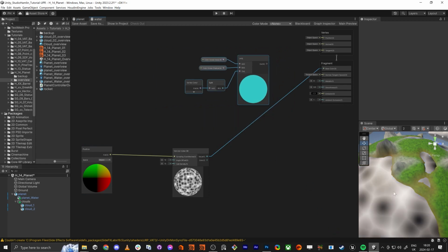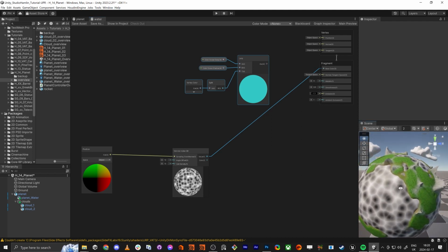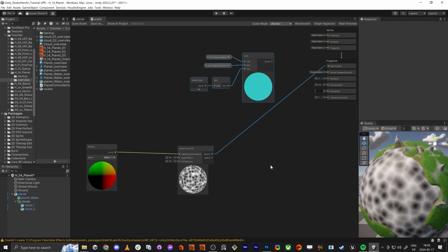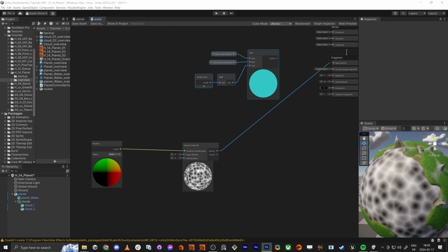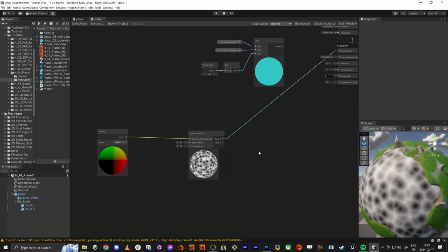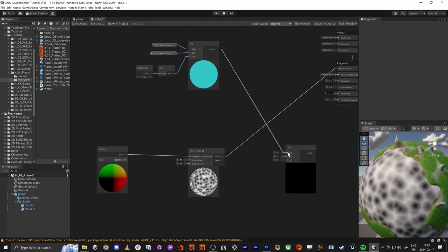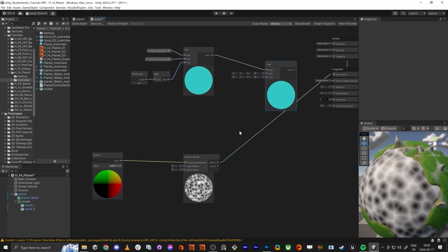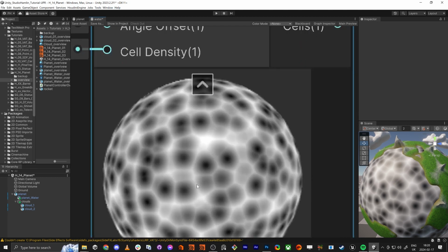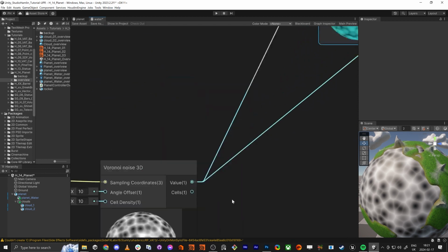And you see we're starting to get these wavy shapes, right? And we want to use this as a mask. So if we do a lerp, and this is the base color that we made in the previous tutorial, and if we do this one, then everywhere where it's white, it's going to be the new color, and black is blue.